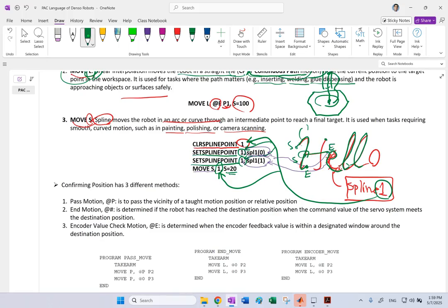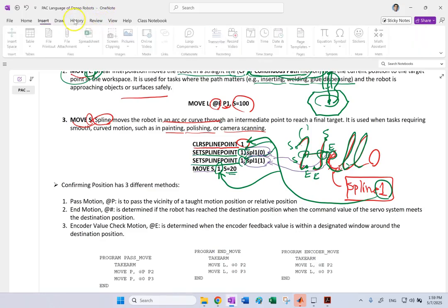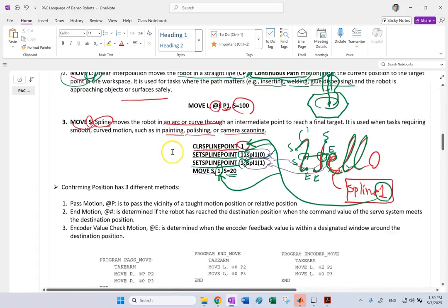And then I come here, start this one, and then maybe end it with this one. Because here I have the sharp corners, I have to switch to a new spline. Otherwise, you will not get sharp intersections, because splines are meant to be smooth. Every point has derivatives, so pay attention to that one. So we have seen approach and move.